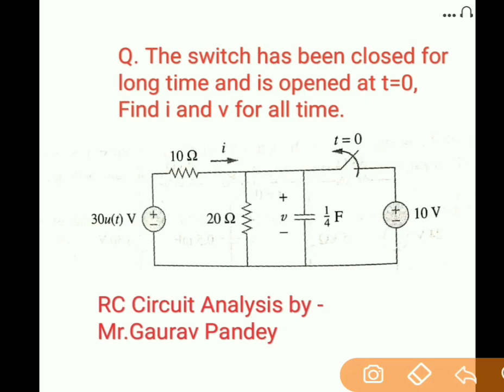The third thing one can ask is, what is the order of this particular circuit? The order of the circuit is determined by the number of storing elements. In this particular circuit we have only one storing element, so the order of the circuit is first order. If there are two capacitors and one inductor, then the ordinary differential equation would be of third order. The number of storing elements tells you the number of state variables, and that is equivalent to the order of the system. So this is the basic concept.